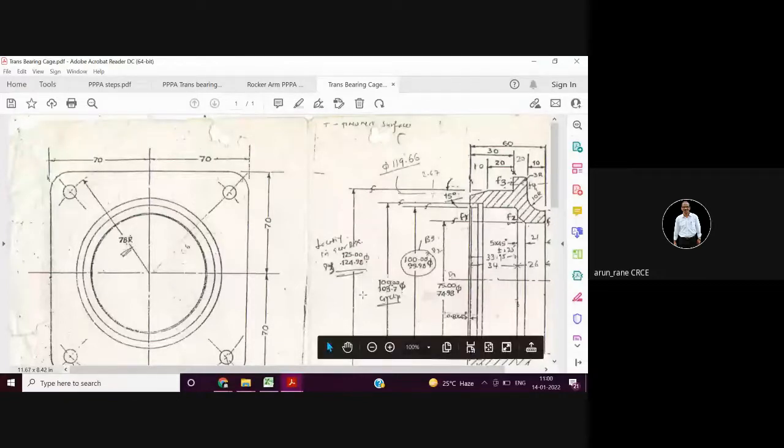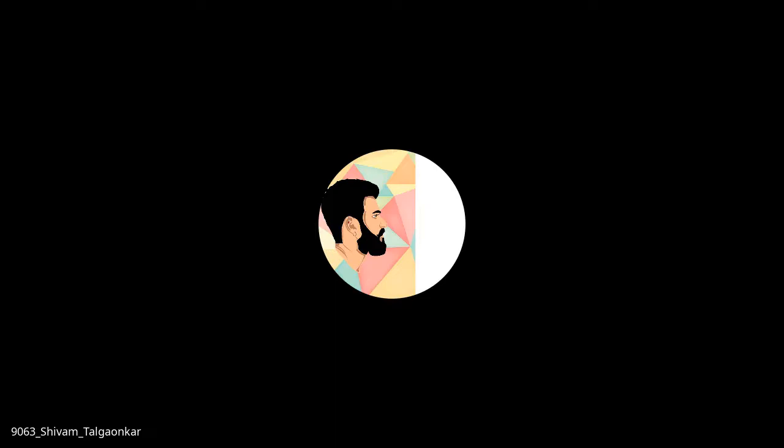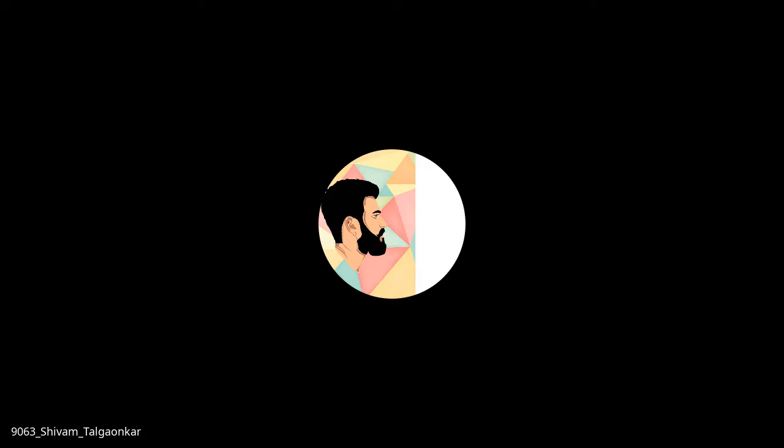This is 109.00 and 108.7. 108.85, plus minus 0.15. Exactly how do we do it? Look, total tolerance is 300 micron, divided by 2 is 150. And we take the average of 109.00 and 108.7, which is 108.85. So it is plus minus 150 micron.